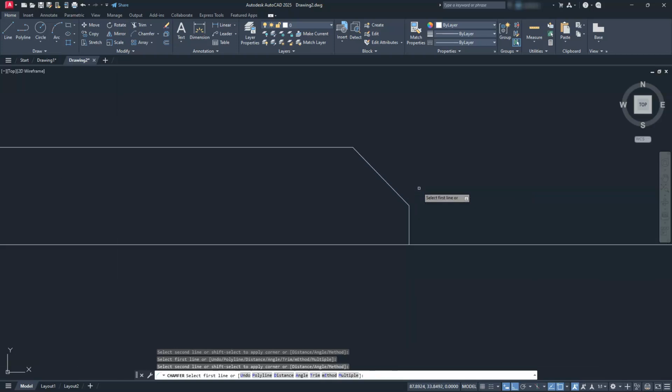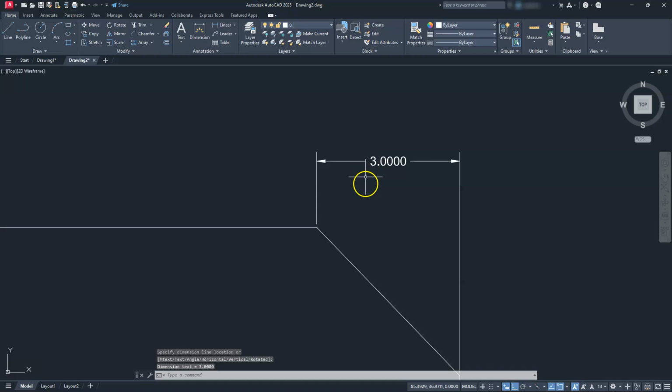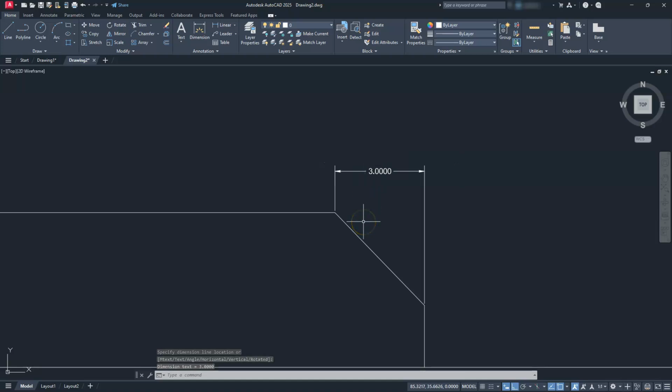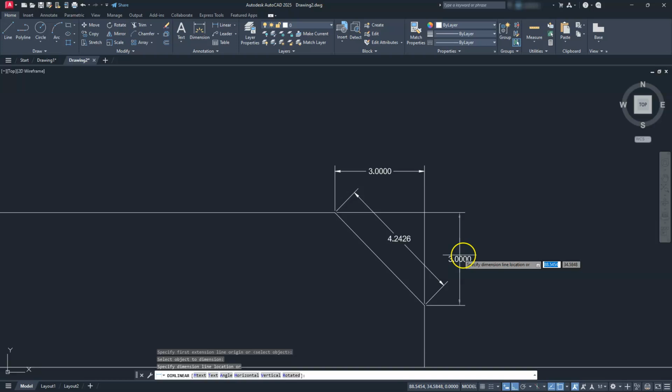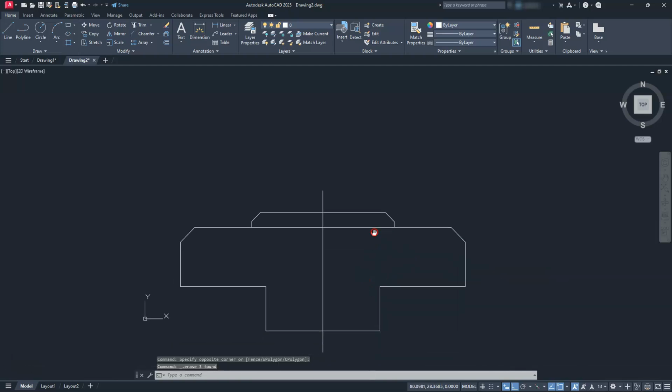exact same thing. Now I'm going to go ahead and zoom in here and just check this distance for you, just to show you. So when I go to distance, and I'm just using the type in command for it, but it's just DLI, and I show you here that that distance is still going to be set to 3 going from that, as opposed to giving you an angle that is here, right? So that 3 does not mean this. Just keep that in mind, that 3 means that it's going here to here. All right, let's go ahead and erase this. Then let's zoom back out.